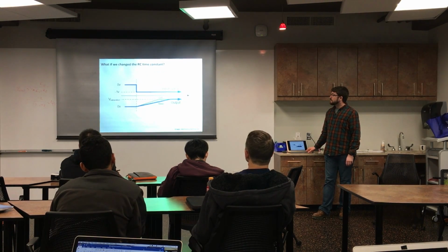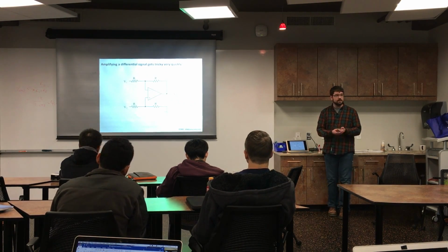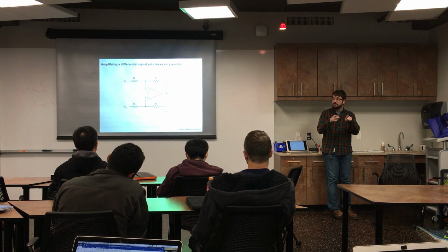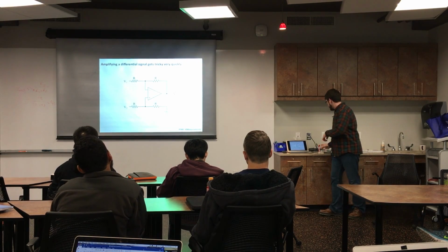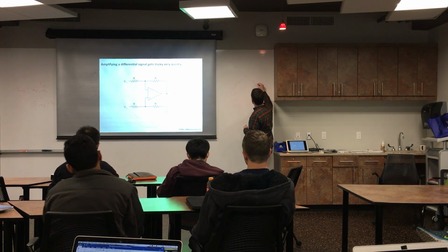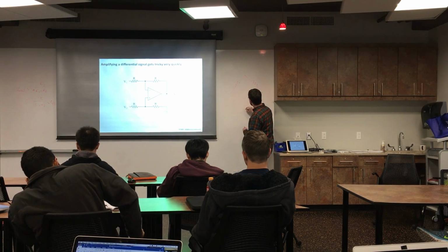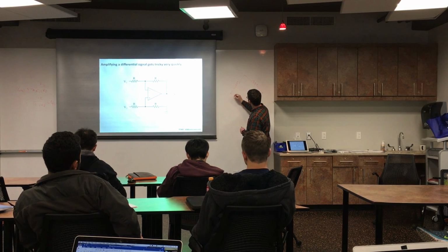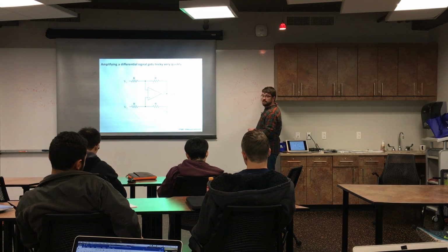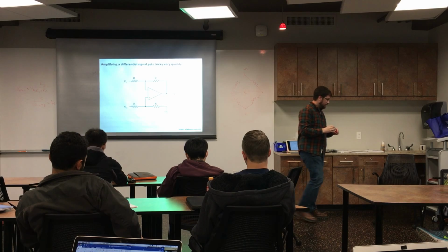What if you have something like your Wheatstone bridge that you just created, and it does not have a ground referenced output? You take the difference of the two terminals coming out. You've got, say, +5. You're measuring the difference between these. That tells you the strain.